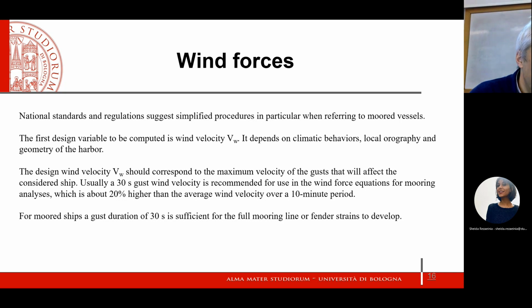And when you have an observation every 10 minutes, this is not the max. We assume it's the average. It's not the max, because if you have just points in time, it's very unlikely that you get the max of the observation in these points.